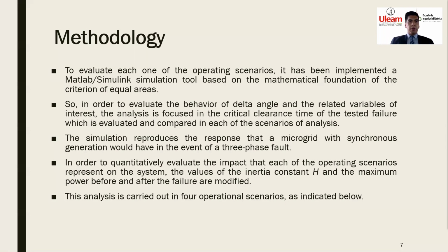Methodology. To evaluate each one of the operating scenarios, a MATLAB Simulink simulation tool has been implemented, based on the mathematical foundation of the equal area criterion. So, in order to evaluate the behavior of the delta angle and the related variables of interest, the analysis is focused on the critical clearance time of the tested failure, which is evaluated and compared in each of the scenarios of analysis. The simulation reproduces the response that a microgrid with synchronous generation would have in the event of a three-phase fault.